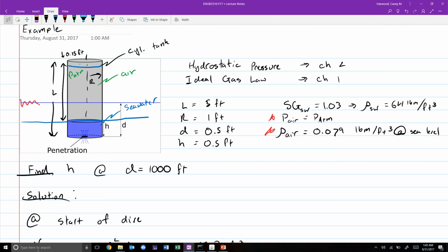So what we get from that is, as this thing goes deeper, its net density is going to increase because the water level is rising, and this lighter gas is getting more and more compressed and more dense as a result. Its tendency to sink is only going to increase with added depth.